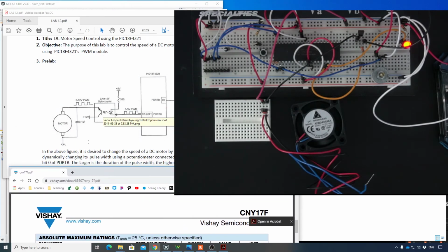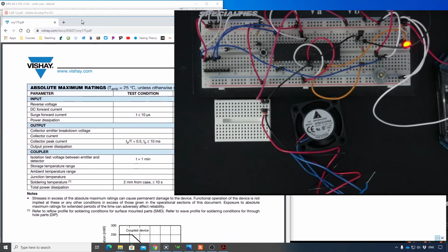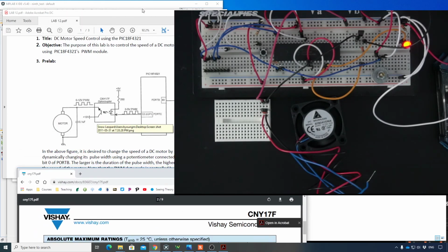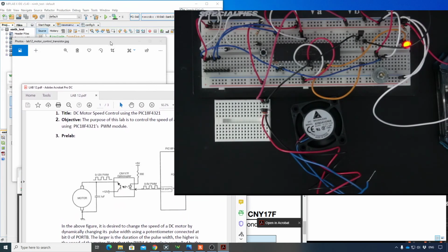If you have a motor that needs 12 volts, you're going to have to figure out a power supply that gives you 12 volts. In the 12 volt case, it might work because 12 times 0.1 is 1.2 watts. So a 1 watt motor is reasonable, but in my case, it didn't work because I couldn't draw the 150 milliamps I needed for maximum speed. Okay, so something to think about. This is why I selected not to use the optocoupler.